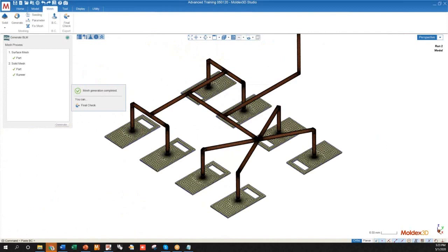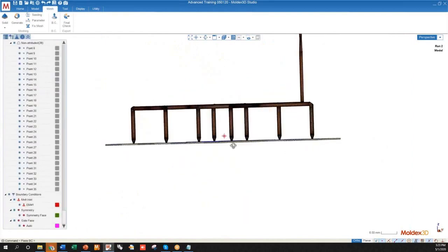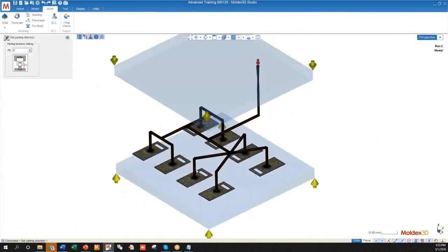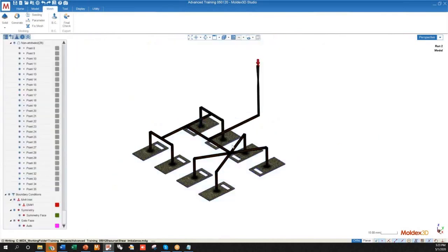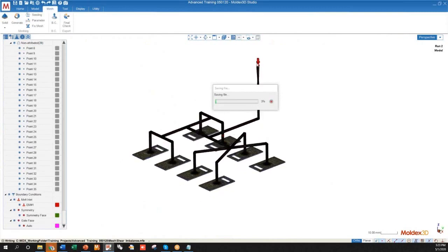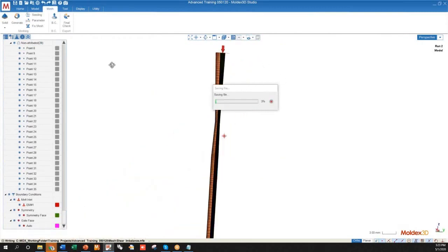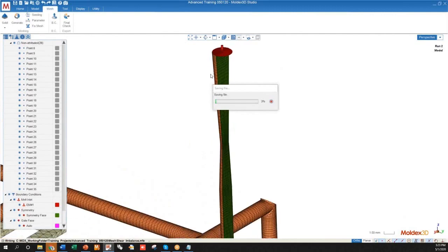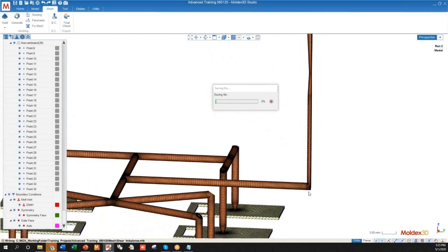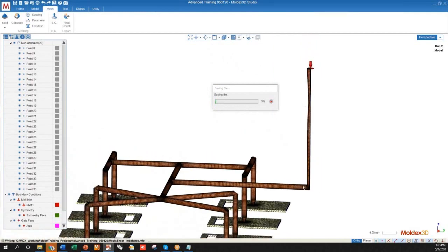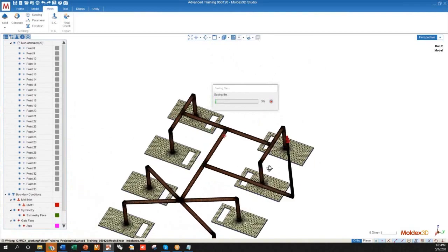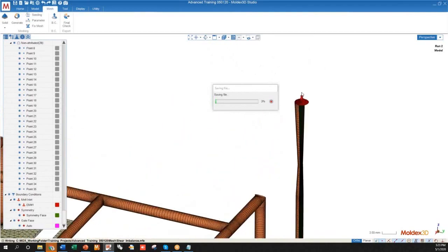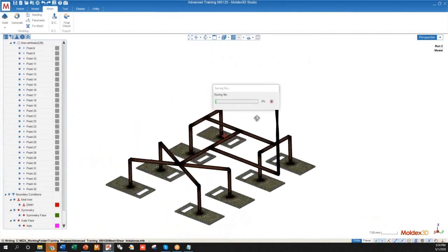In an ideal world, we would be able to just have the exact same flow balance coming out of our gate as we do at our nozzle. So we would just be able to basically deliver our melt directly from our nozzle to our gate without any sort of changes. But realistically, unfortunately, because of how the polymer moves and how the polymer interacts with other polymer chains, we aren't able to necessarily get the same distribution of temperature from our gate to what's happening at the nozzle.